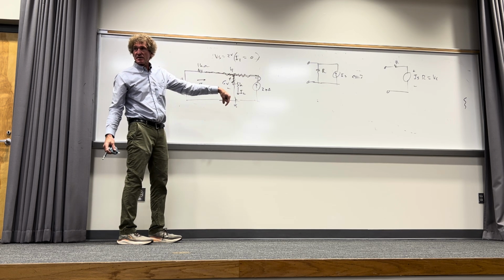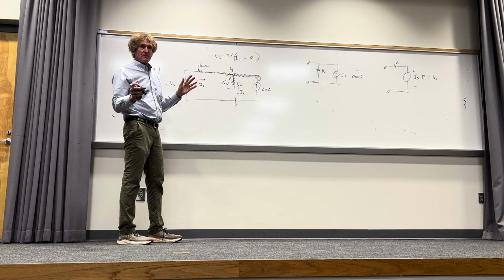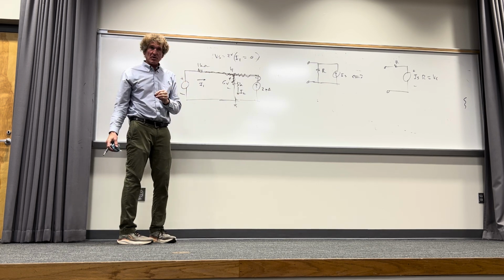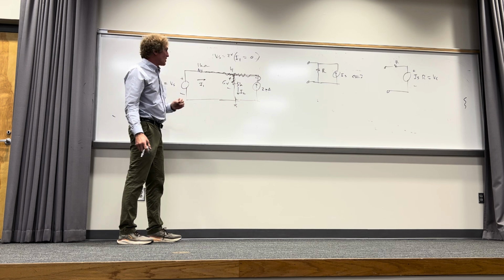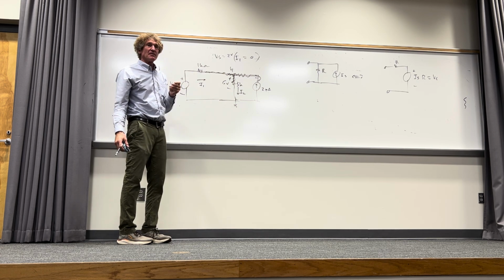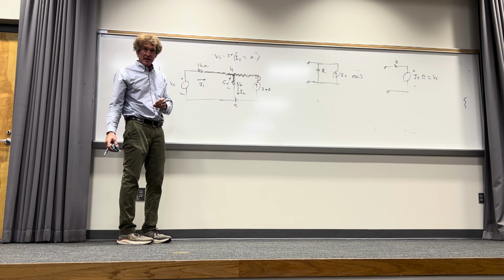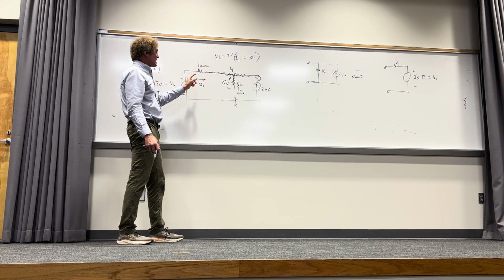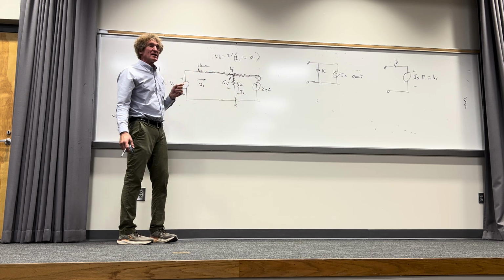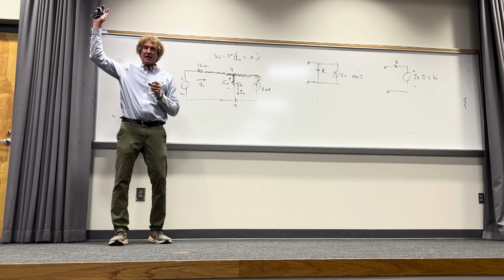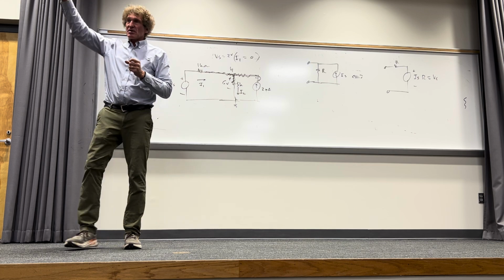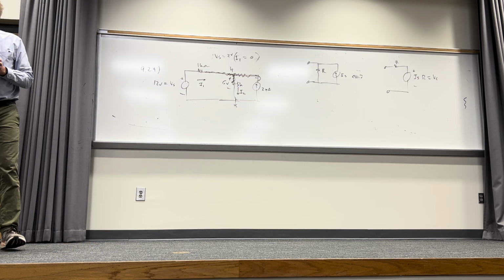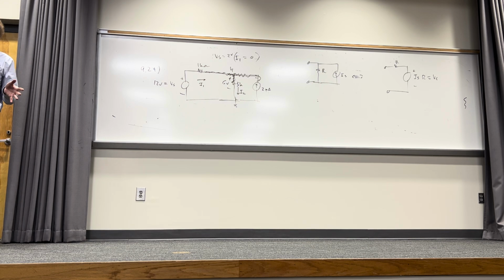Over here, guys. Francis? We can do that. Once we do that, we can figure out what V1 is. Do you all agree with that? If we have V1, we can get I2 by dividing V1 by 3K, right? And if we have V1, we can go ahead and say (VS minus V1) divided by 1K would be I1. How many see that? I don't want to waste time today. Do you all see it over here? Your head's tilted like this, like I don't believe you. I'm trying to be honest, trying to be as clear as I can.